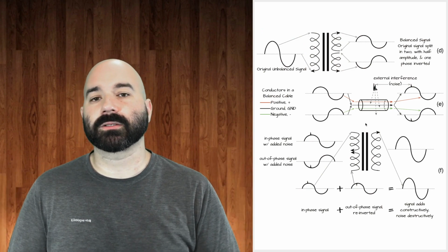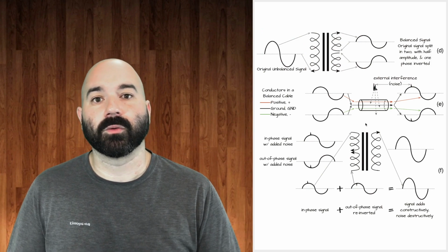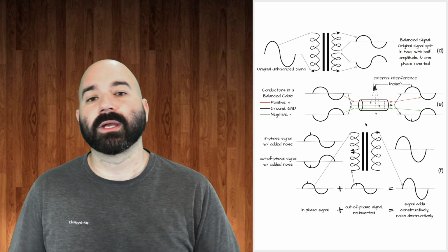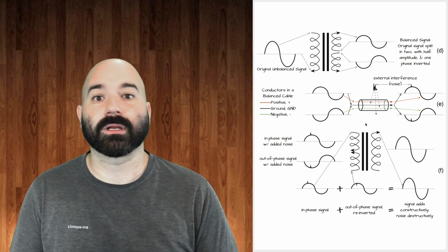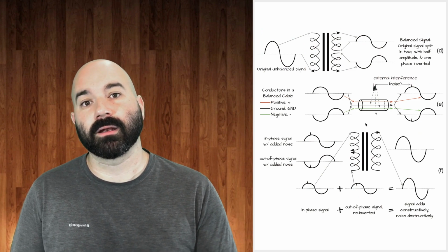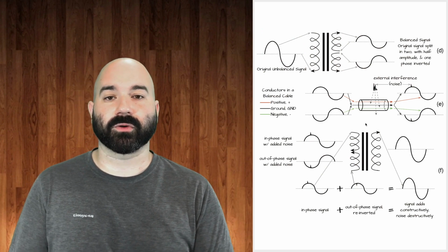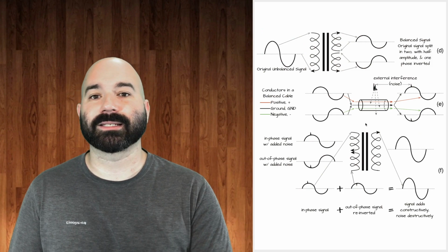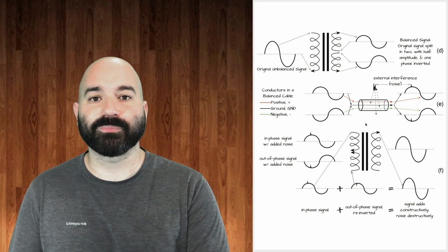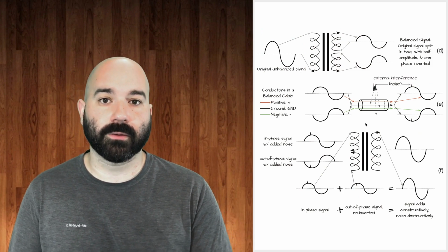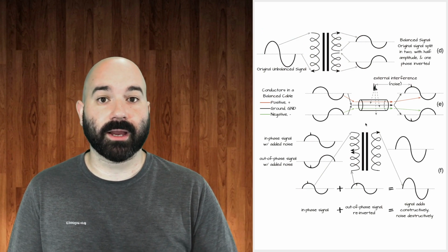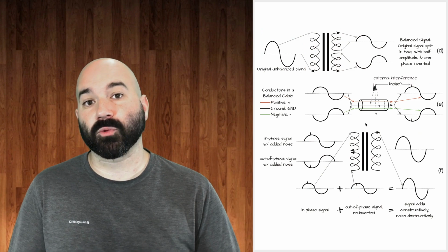And so that's going to cause what's called a ground loop, which in America, with our electronic system that we have, is going to be a 60 hertz hum that you're going to get. In other countries with different protocols for electricity, that'll be a different frequency, but in America, that is a 60 hertz hum. And so if you hear a 60 hertz hum, it's either that you're really close to another sound source and you're just getting EMI, or it's most likely a ground loop.